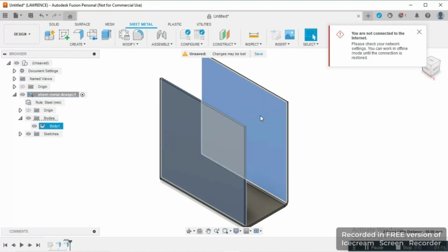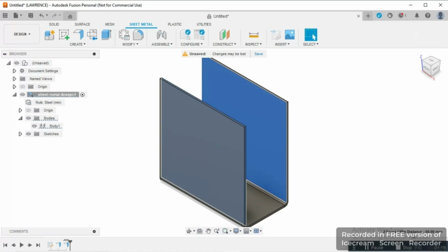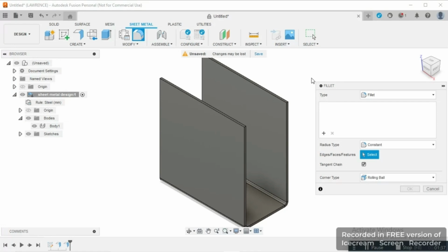We can see that to be 60 millimeters, and that was the exact length we selected from the onset of the design. Now calculated from the inside, not outside. High datum can have significant impact on sheet metals that need precise measurements. We will now add a round fillet to the top edges to create the rounded portion of the design.